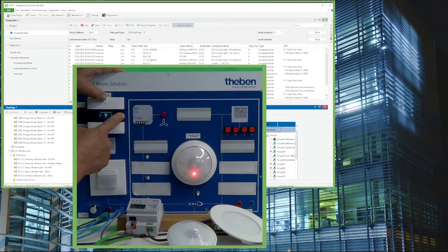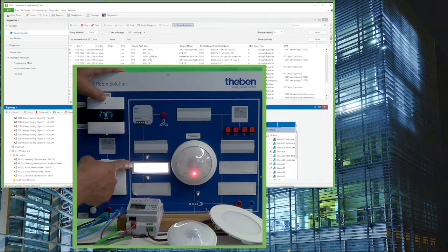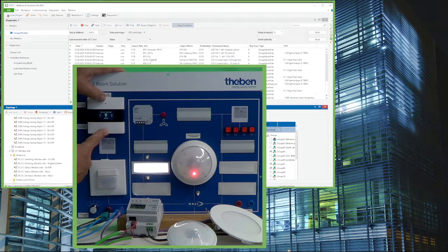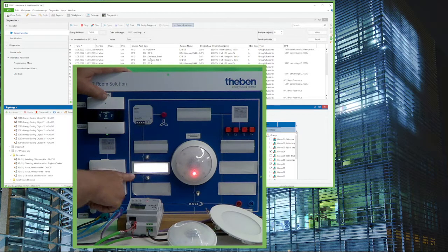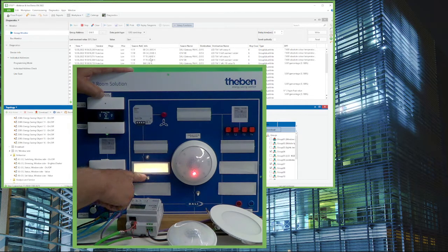So then I have, for instance, here the universal light, this tunable white, dimming up, dimming down. I think it is visible for you. So next step, from this, let's say 3700K, which is the middle range of the color temperature, I increase now to 6000K, and probably you discover the light becomes more white, icy cold white, and dim down to 2500K, and in a few seconds it turns now more to a yellow light.